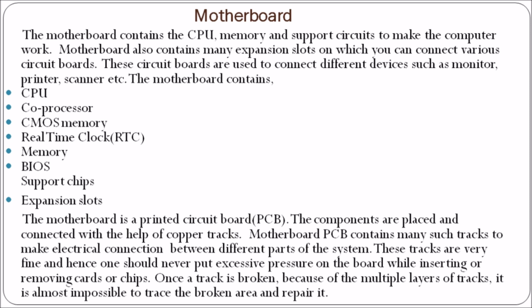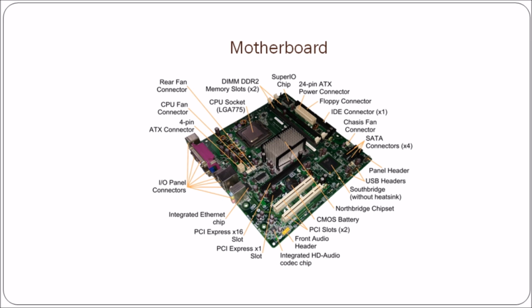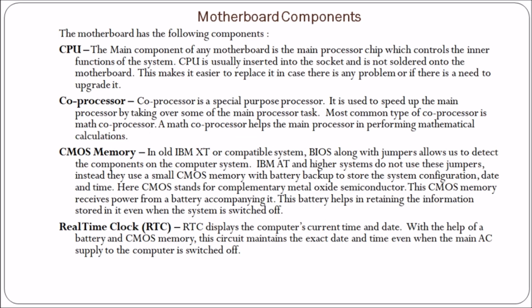These tracks are very fine and hence one should not put excessive pressure on the board while inserting or removing cards or chips. Once a track is broken, because of the multiple layers of tracks, it is almost impossible to trace the broken area and repair it. So this is the motherboard and different parts of the motherboard are displayed. The motherboard has the following components.